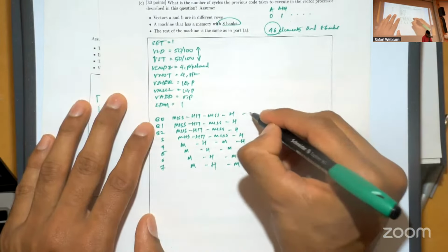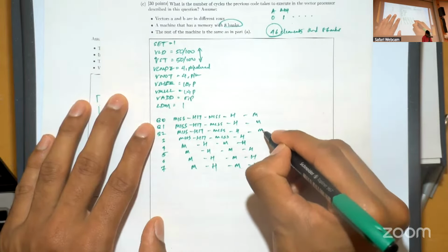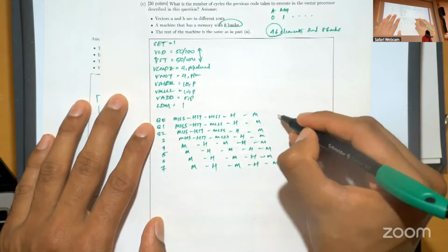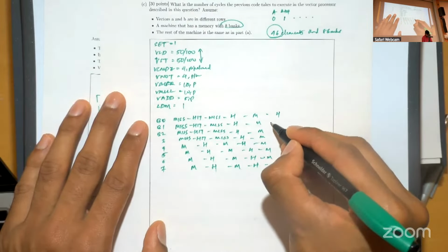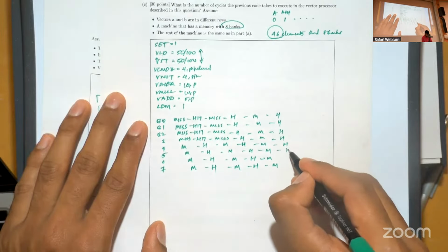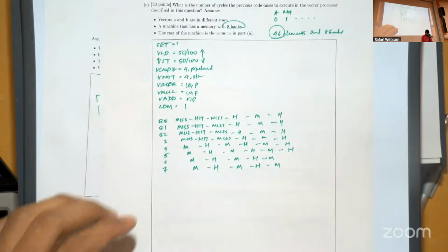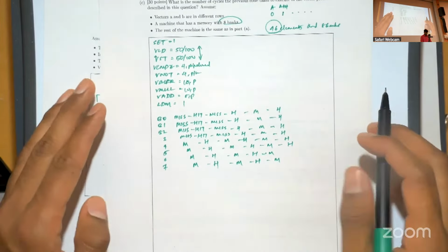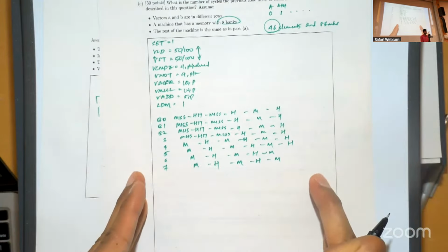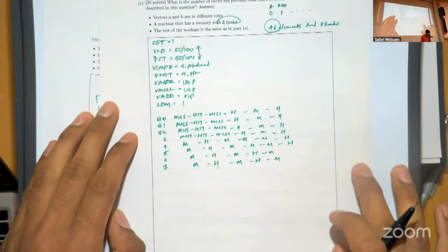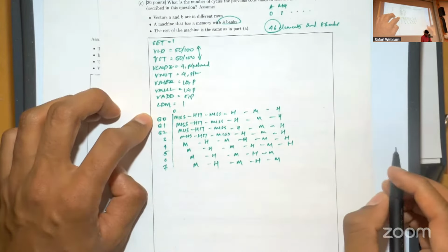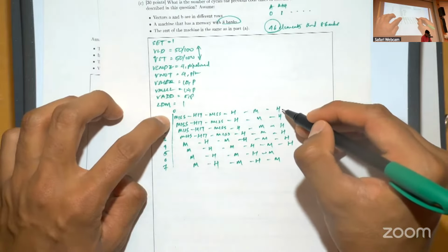Right? We're going to have another set of misses because this is 32. Here we would have 40 memory accesses done. And this will be 41, 42, 43, 44, 45, and 46. Your memory access latency for the VLD instruction will entirely depend on the longest running data fetch from the different banks. So B0, let's say, starts at time 0. It will take 6 memory accesses and it will be done here.